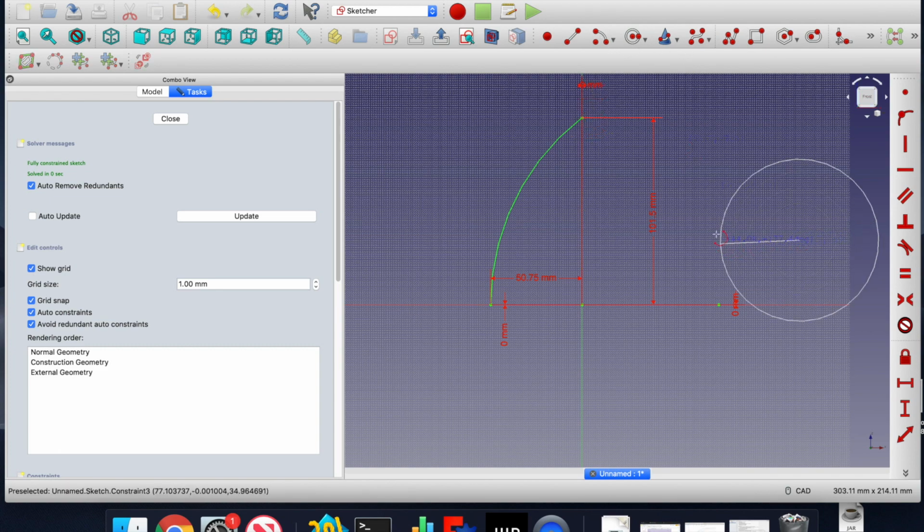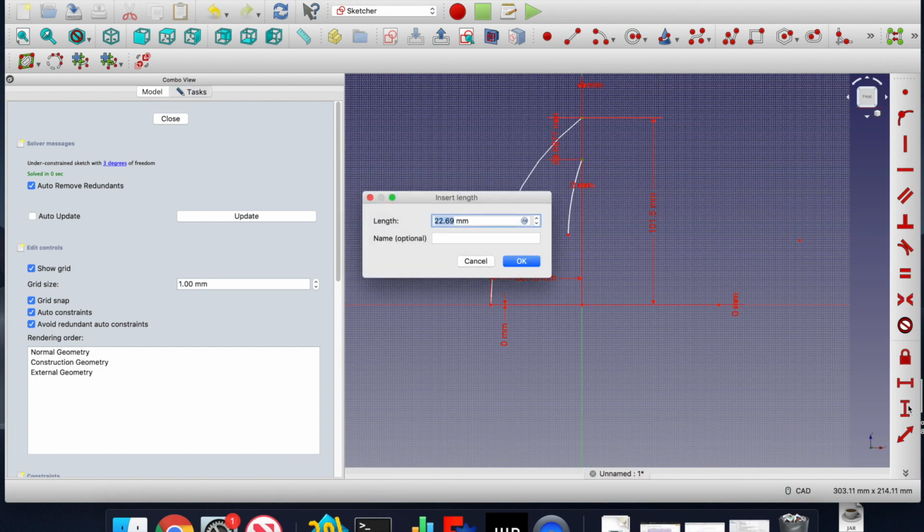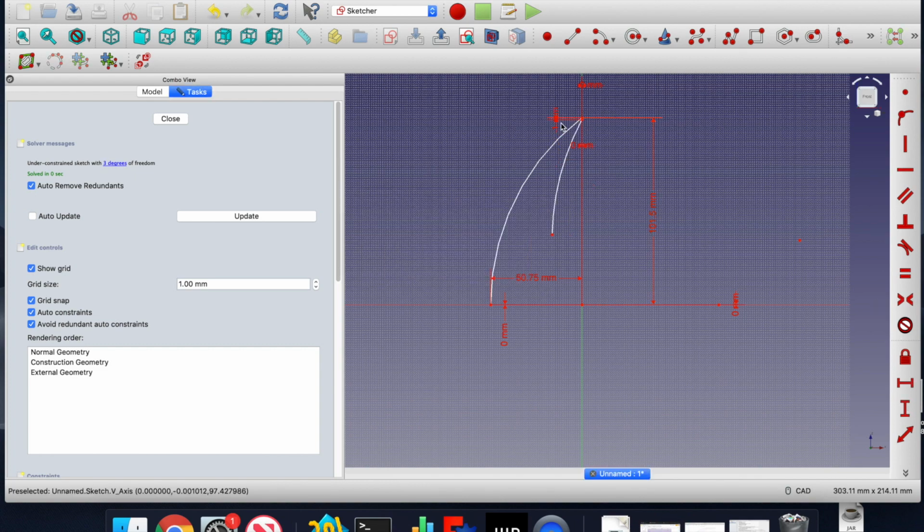We have to make a complete surface here, so I've got to define the inner side. So I'll make another arc. Again, these points don't mean anything. This guy is going to go over here, right on there. Basically, I want this to be 1 millimeter thick. Not sure exactly the best number, but 1 sounds fine. This guy would need to be on the axis.